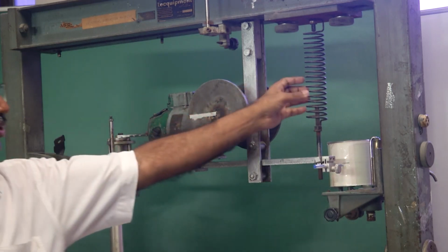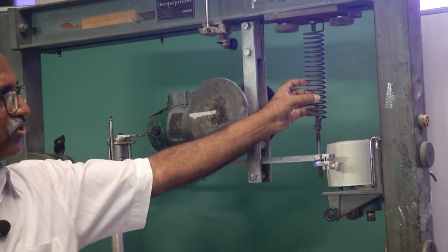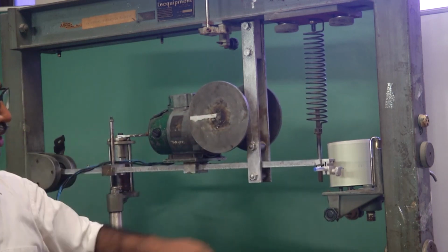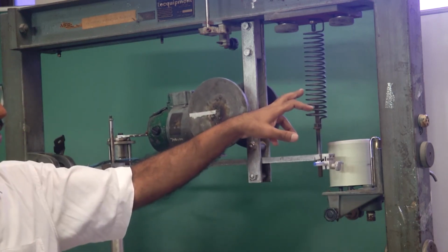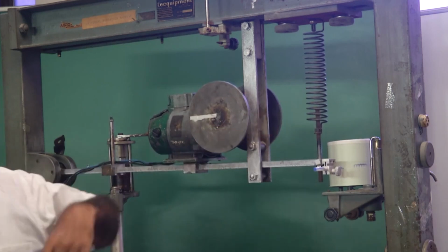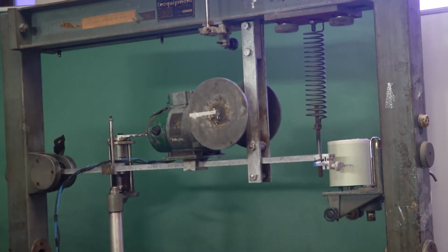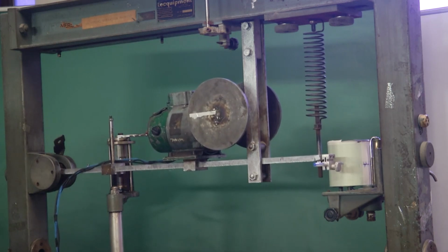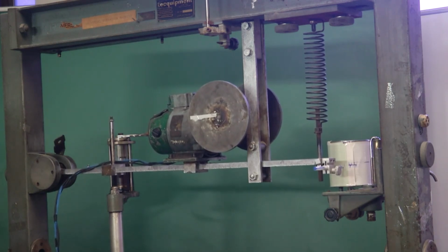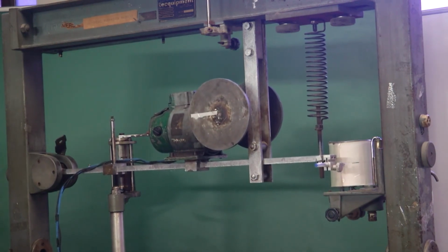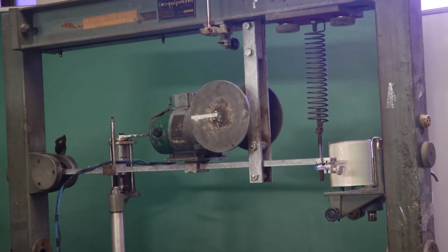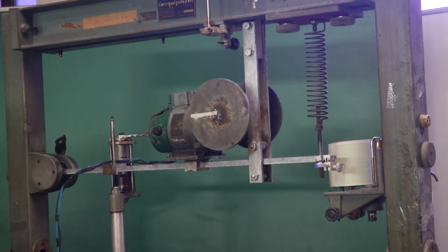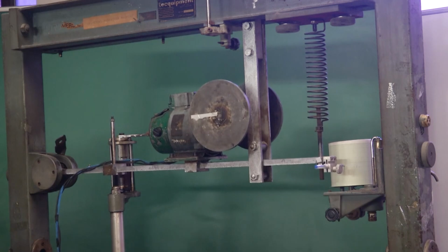But definitely we notice that the spring is getting stretched and compressed, and no matter how small, there would be some hysteretic or structural damping because of the cyclic extension and compression in the material. So, intermolecular friction is going to create dissipation of the energy, which is getting converted into heat.